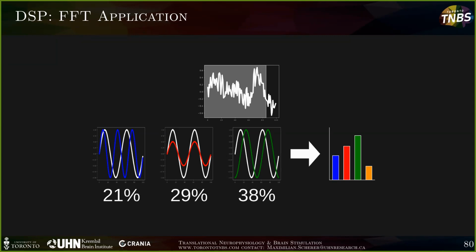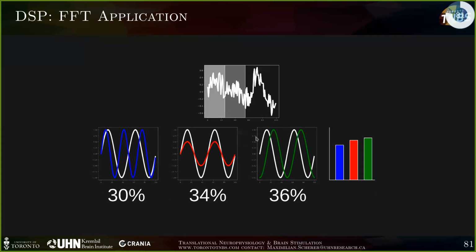The other answer, that noise cannot be handled at this step, is luckily incorrect as well. We can handle noise at this step. It's not like we have to forsake all hope yet, assuming the noise is limited to some degree, but we can handle it. What we can do is provide the FFT with more data, but we don't do it in one chunk. We do multiple FFTs, have multiple windows here, and evaluate those windows individually, and then we average across those windows.